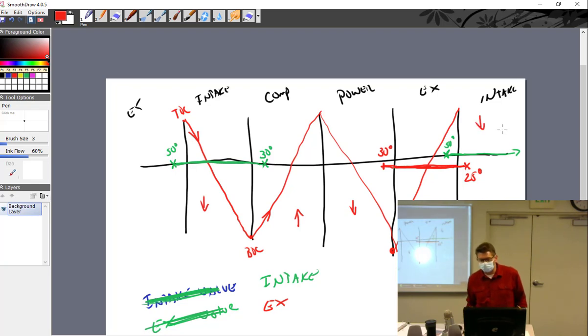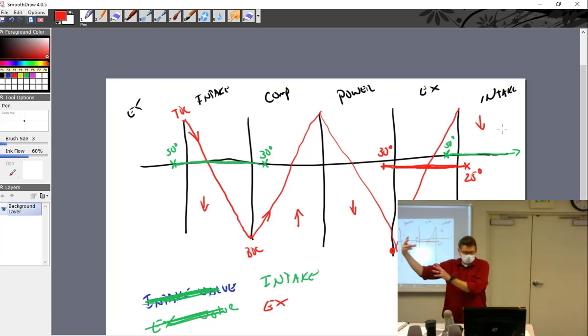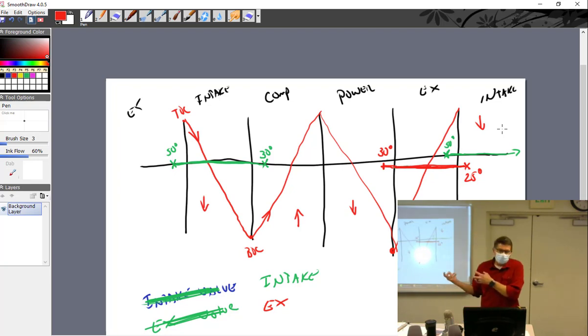Even though the piston is now working its way down, it's starting to draw in stuff, which you would think would cause the exhaust gases to go up the tailpipe, in and down in the cylinder. It's not, because you have inertia, which means these gases are actually flowing. They've got kind of a mass to them, so they don't want to just stop suddenly. So they're just going to keep carrying out, and it kind of draws behind it the rest of the bad gases and brings in the new fuel-air mixture. Ta-da! That's how that works, and that's why it looks like that.